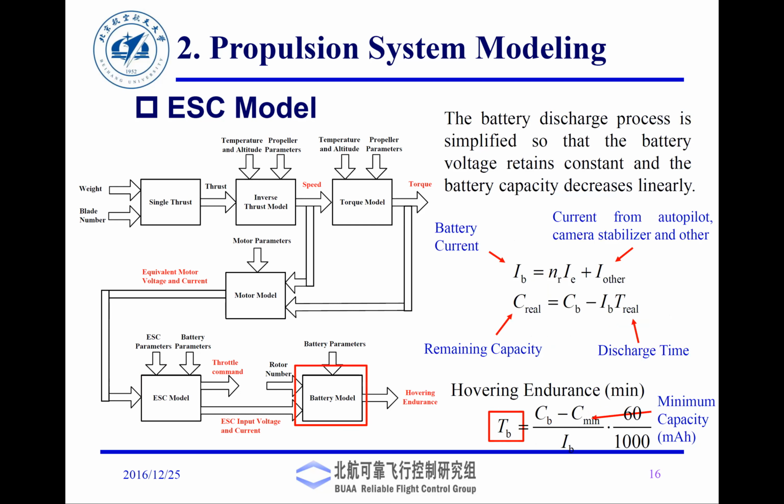Then if you want to decide the battery capacity, once you have identified the number of ESCs and their properties, you have to take into account the other things that you are running, like autopilot, LEDs, grabber, gripper, some sort of GPS receiver, and so on. And then all that load gets added when you decide the battery.